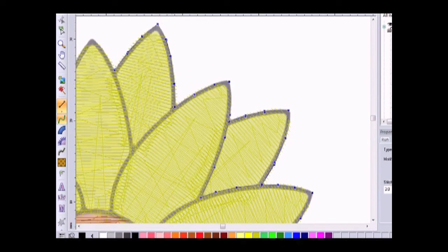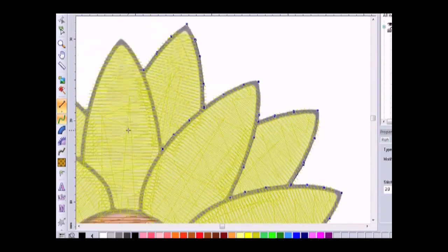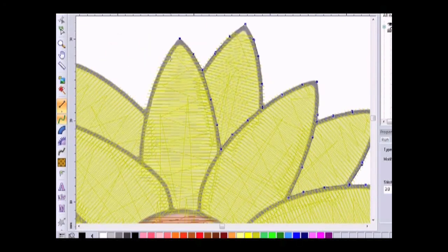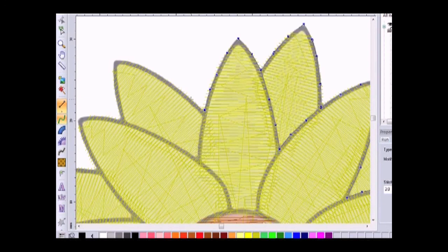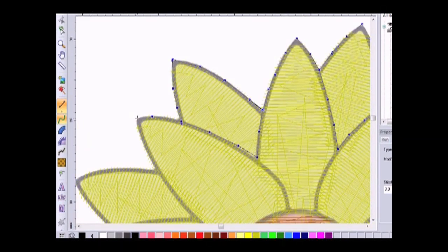If you have too many points in a design, what you're going to do is make your machine have thread breaks, needle breaks, bird's nests. Too many stitches in one place on any design will cause all of those things to happen. So I want to make sure that I path around this design knowing that I'm not coming too close with my points, but completing each object with two paths, and then I'll continue on to the next.